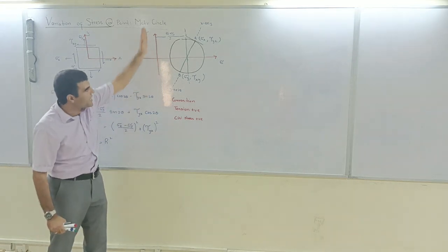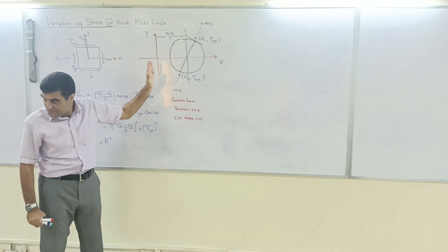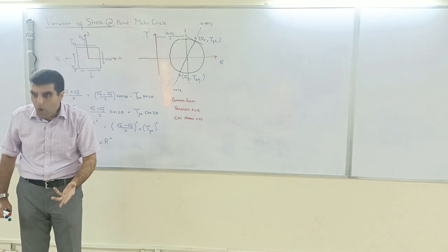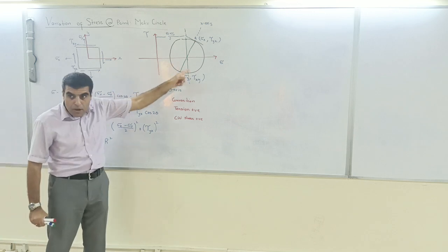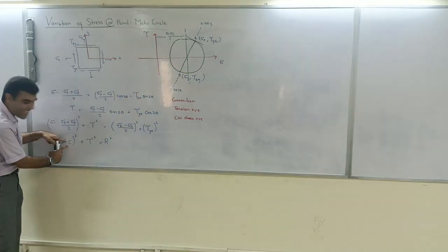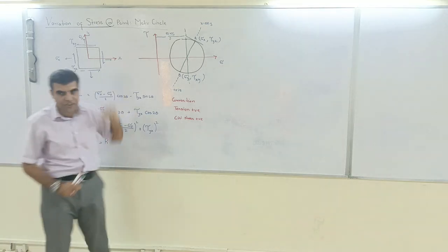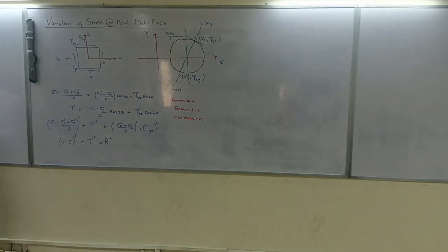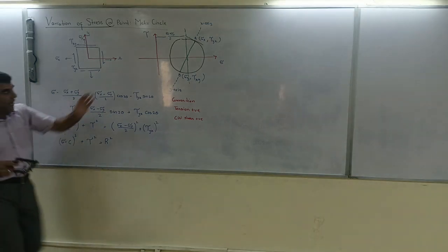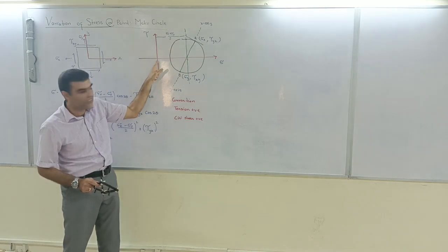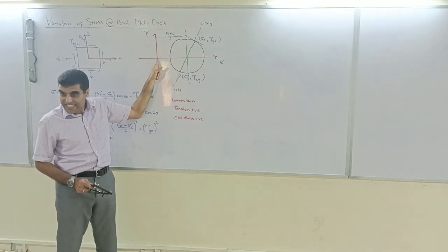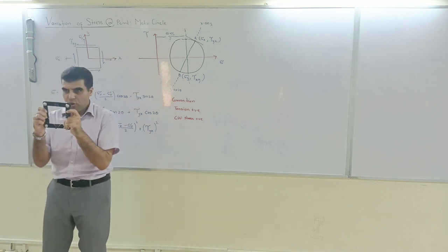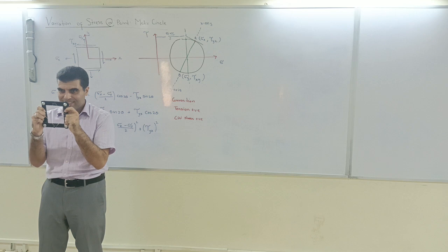Now if you take your shear, your stresses would be 0. In this case it's not 0. But if your centroid C is 0, then your axial stress is 0. So I can demonstrate that to you. Look at that. Imagine your Mohr circle is at the origin. If it is at the origin, that means that you have only shear. So I draw only shear.